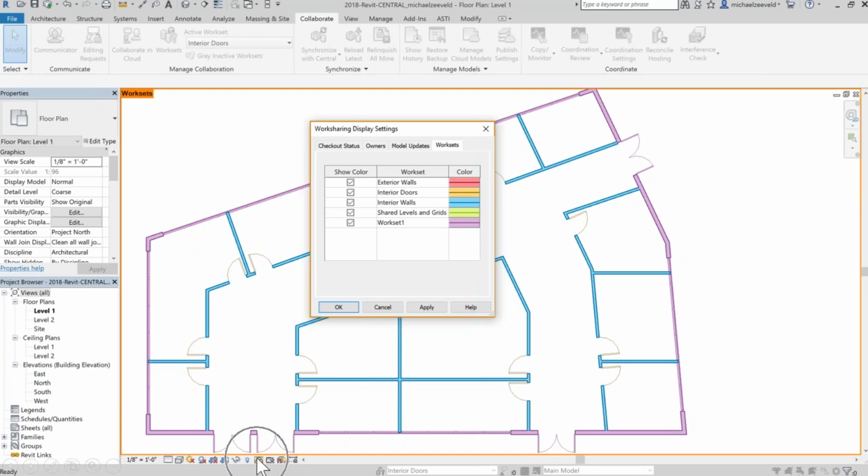It looks like just 3 little colored balls or shapes, and say, show me what these different work sets are, based off of color. So here's my interior walls, they're all blue, and the exterior walls are this purple color or whatever. So I can visually, quickly see what work sets are going to be on what, or what I might be responsible for. I'm going to be responsible for all the blue stuff, okay? And then Rick is going to be responsible for all the exterior stuff. So that kind of scenario.